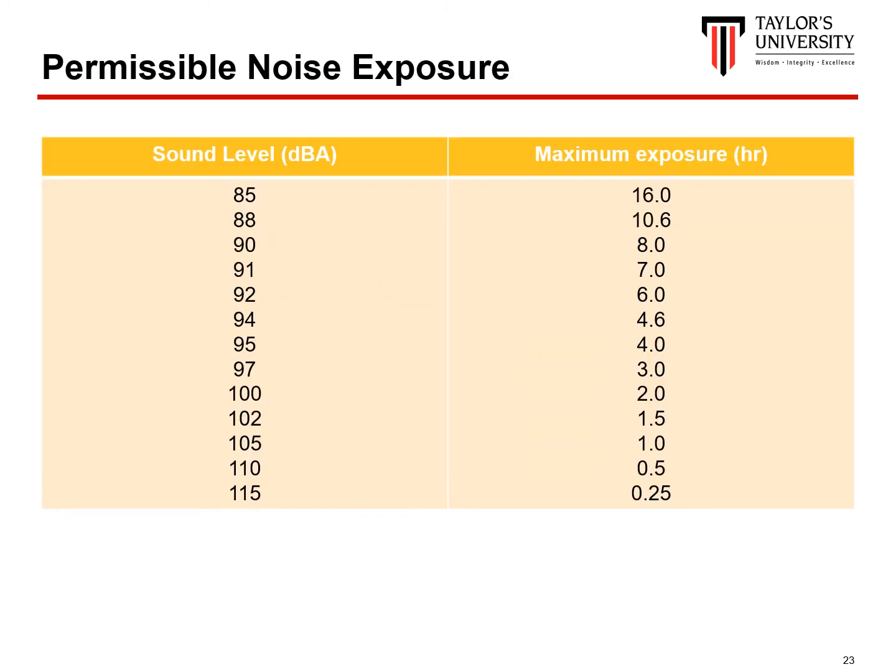An absolute sound scale in dBA, for absolute decibel, is defined by establishing an intensity reference. For convenience, the hearing threshold is set at 0 dBA. So table 3.7 shows us the dBA levels for a variety of common activities. And the permissible noise exposure level for a single source is provided in this table shown in this slide. So that's the sound level in dBA and the maximum exposures at this level.